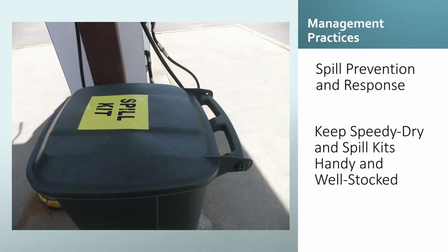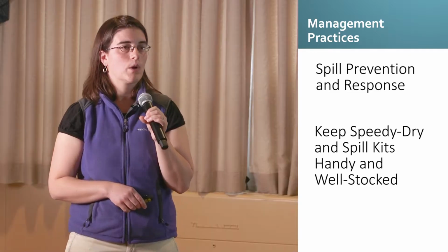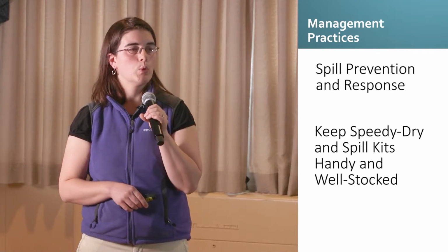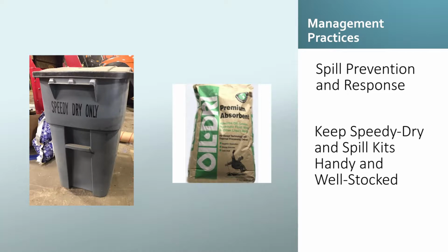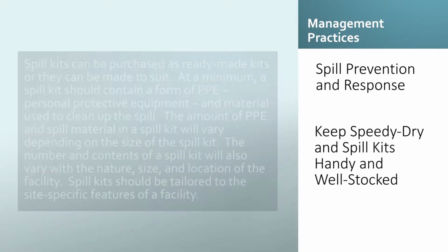You could take a 55-gallon waste container and fill it with all the types of spill response equipment that you may need, booms and pads or speedy dry. And then it's advisable to have ample supply of speedy dry, various locations throughout your facility.